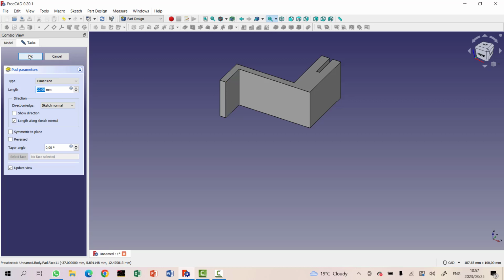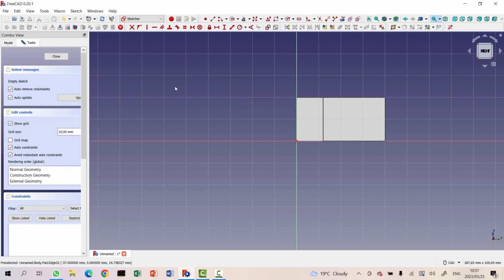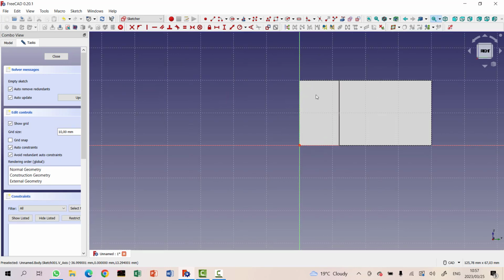So let's click OK, and then I'm going to click that side, and we'll put in holes there. So I believe that would be it here. So we're going to put the hole in there, and remember our screws are 3mm screws, so we are going to use 3mm holes for this. I'll put 1 hole there, which is a little bit big, so we'll just leave it like that, and 1 hole there. Okay. That's fine. We'll set them up.